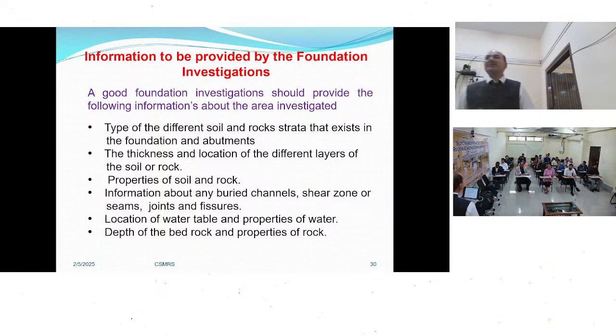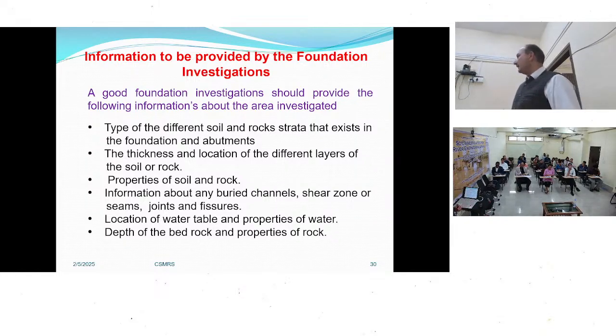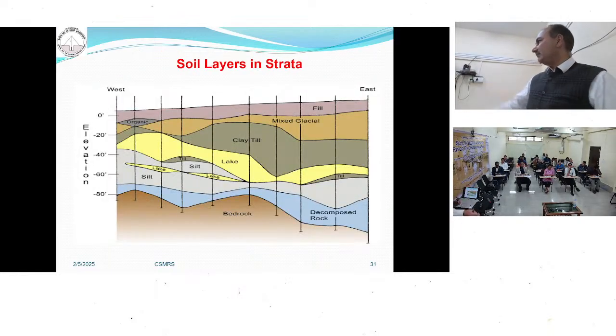So basically foundation investigation means whatever your site is, what are the different layers, whether they are soils, rocks, weathered rocks, what is their location, what are their properties. It could be there are some faulty zones, shear zones could be there. So your foundation investigation should be sufficient enough to identify all these things. What is the water table? So in that way you have to carry it out. And what is the depth of the bedrock? So this is the picture of the foundation investigation.